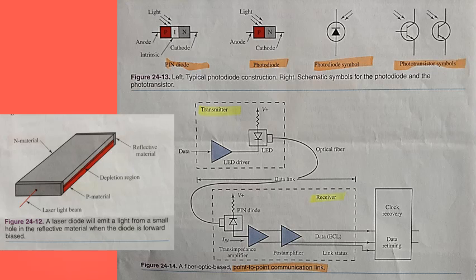Fiber optic receivers. Receivers use photodiodes to convert the light energy back to electrical energy. Some of these diodes are the Avalanche photodiode, the PIN diode, the phototransistor, and the photo Darlington, figure 24-13, top of the screen. Phototransistors and photo Darlingtons are not preferred devices for high-speed receivers. The reaction time of these devices is slow in comparison to the Avalanche and PIN diode.